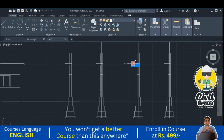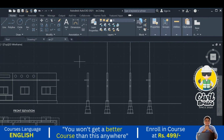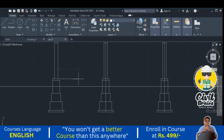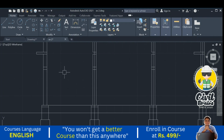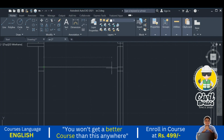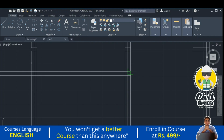So the slab projection, I just delete. Whatever extra part is required, we just draw that one. Whatever is not required, we just delete. Okay, first I draw the plinth level. From here to here plinth, from here to here plinth, again this is plinth. Next I draw the lintel level, from here to here lintel. So that you can easily understand the different levels, I just draw that one.